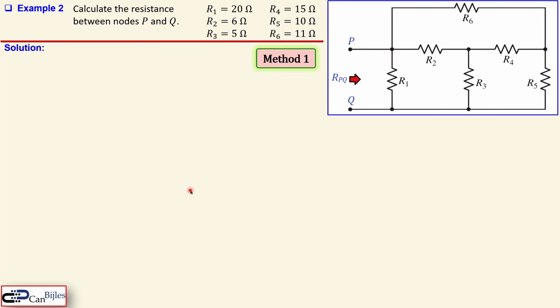First step is, in this case, a method which we call just method 1, where we use the loops. So we again use the mesh current method, but I will also show the same circuit in method 2, where I use the node voltage method, which is then faster in this case. So let's go through the equations first.